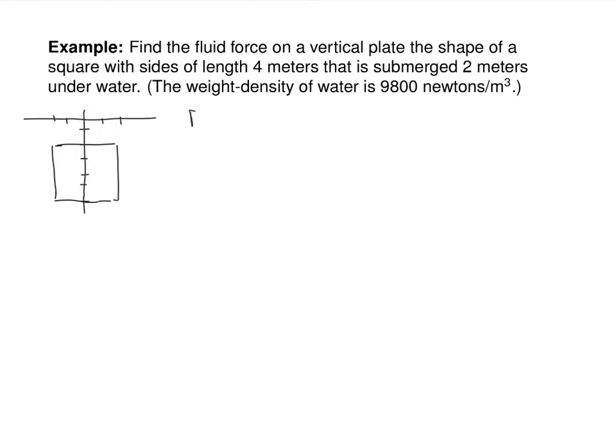Now the general way we're going to find the force is W times the integral from C to D of depth times length of a slice, dy being the little thickness of the slice. So the nice thing about this one is that if you cut your little plate into chunks, the length of each slice is the same. So in this case, we have L of y equal to 4.